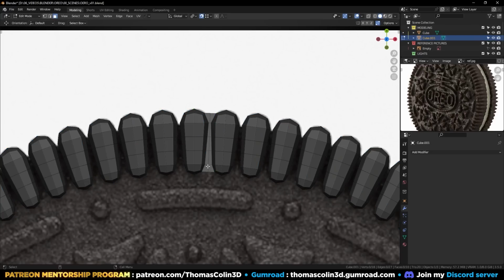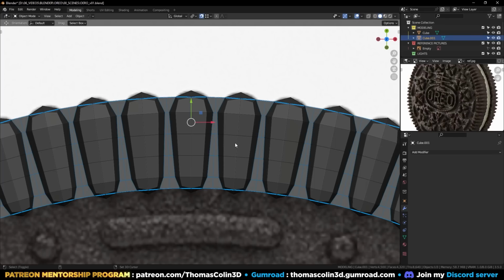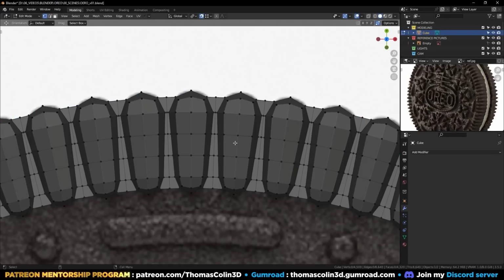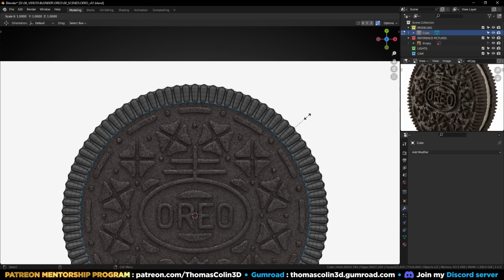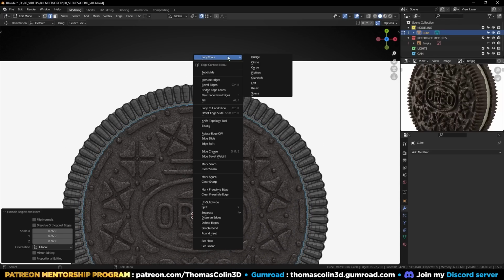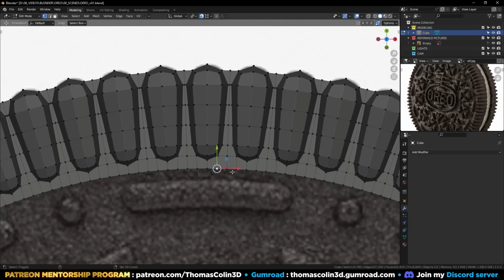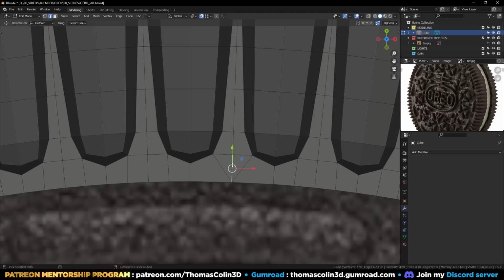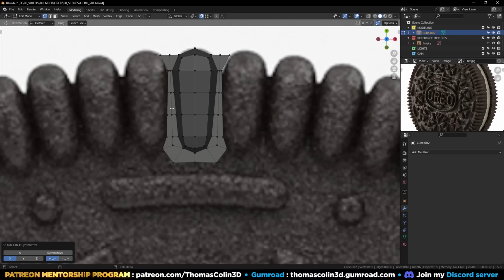And again, go into edit mode, select all the faces, Alt-E, spin. So now select everything, Ctrl J to join, and merge the vertices by distance. Select this border, ES to scale, right click, loop tools, circle. Now I'm going to select this vertex, this one, and then this one, M, merge at center. Select this edge, remove it. Press GG to move this vertex along the edge a little bit. You can mirror this to the other side.